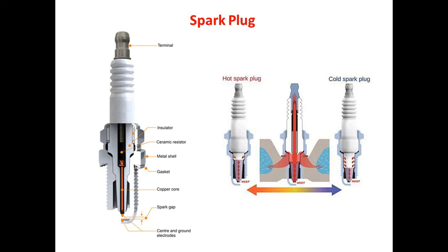Now further, spark plugs can be of two types, the hot spark plug and the cold spark plug. Generally, a cold spark plug has a short heat transfer path and a very small area exposed to the combustion gases, while a hot spark plug has a long heat transfer path and a large area exposed to the combustion gases. Generally, in most automobiles, the hot spark plug is preferred.